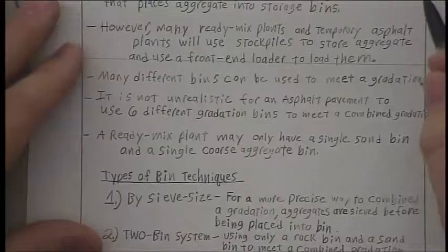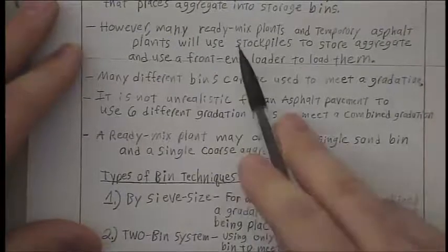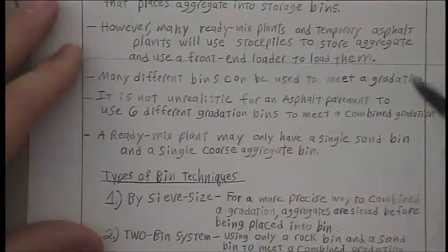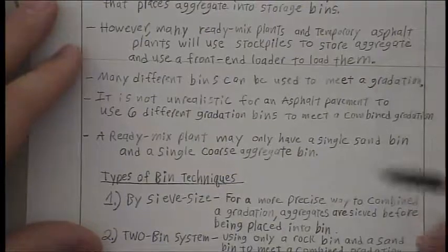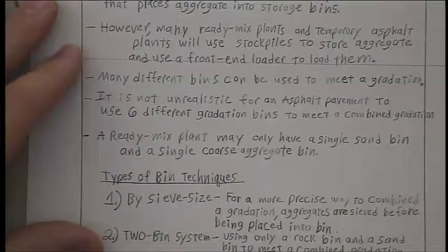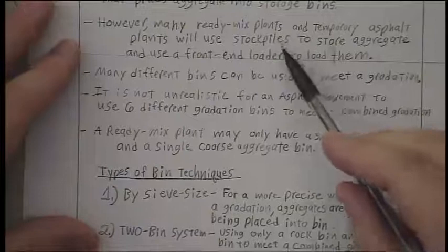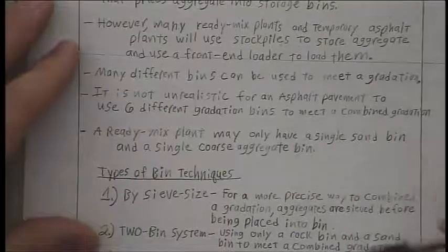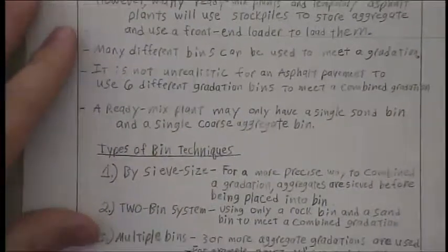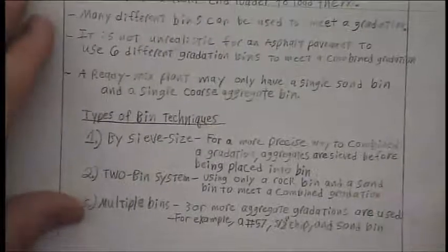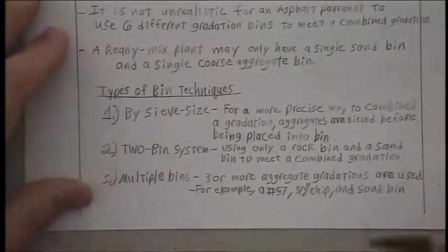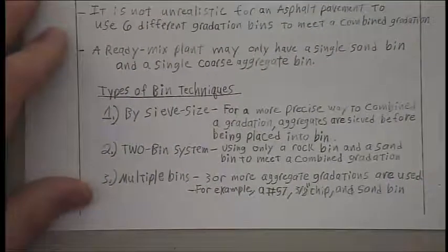So sadly, a lot of ready mix plants and asphalt plants, they may be temporary just for a little bit, and they'll use stockpiles to store it, and they'll load it up with a front end loader, and you have a lot of segregation issues, and they don't understand why their gradation didn't perform the way they thought it would.